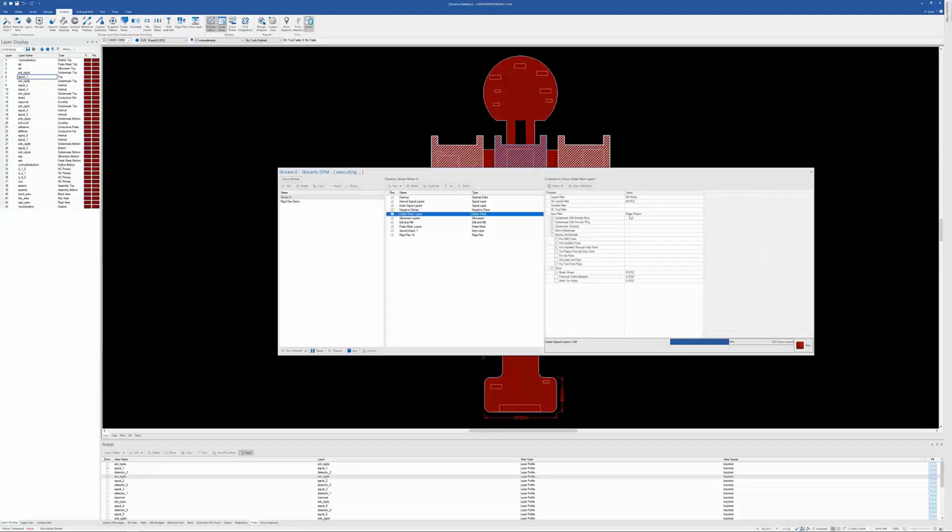Let's go to solder mask. These are specific to solder mask layers, silkscreen, drill and mill, paste masks. If you are creating your own paste mask or stencils, we can even do the ratio checks, the IPC ratio checks. Here's where we added our inter-layer checks, and here's our rigid flex checks. So all of those can be just kicked off, run, and then you validate the results once it's done.